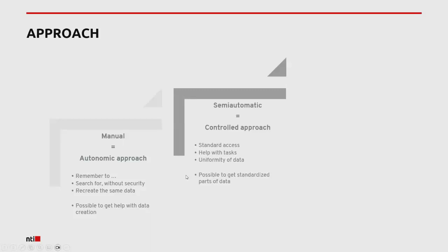The second step could be the semi-automatic, which we also call event-based. So every time you save an Inventor drawing, change a property, check into Vault, whatever event you could imagine, can basically trigger the publish of a PDF file. It could also be a lot of other things that are triggered, but just to give you an example.